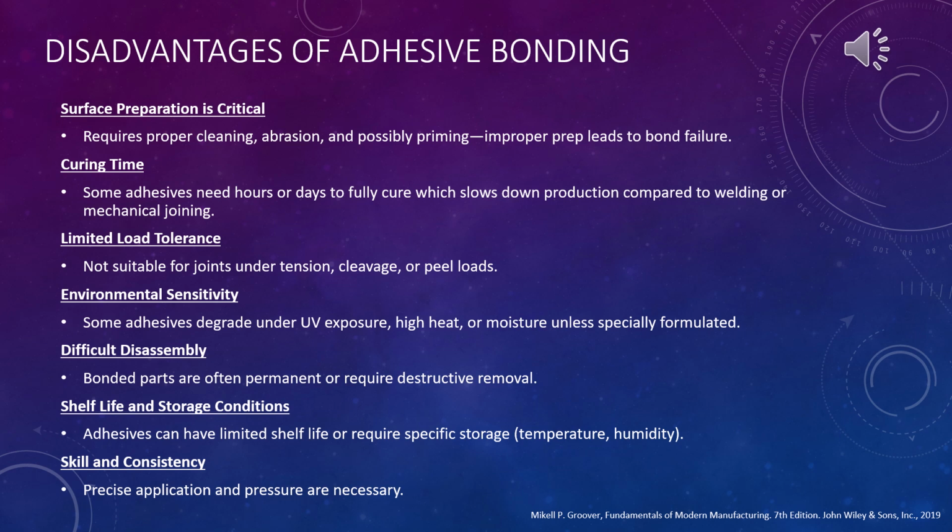Number 4 is environmental sensitivity. Some adhesives degrade under UV exposure, high heat, or moisture unless specially formulated. For example, acrylics are excellent for UV resistance. In applications like outdoor construction or aerospace, specialized adhesives are needed to prevent breakdown over time.